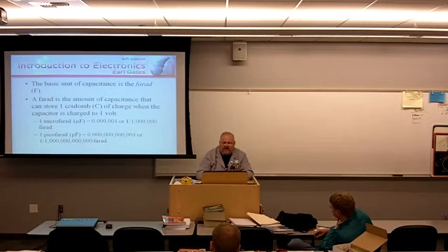Now, typically the values that we're going to work with in electronics are centered around the microfarad. The typical unit of measurement of capacitance is the microfarad, which is times 10 to the negative 6th, and also the picofarad, which is times 10 to the negative 12th.